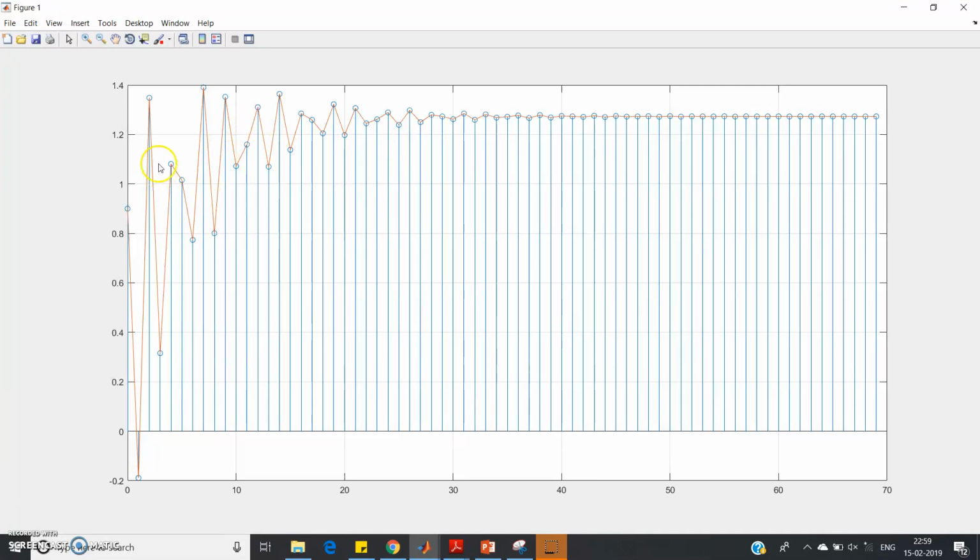So this is the transient response, and it is very important to analyze the circuit. Obviously from this it is clear that the transient response is there for a very small span of time, and for the huge span of time the steady state response is there, but the transient response is very important from the point of view of designing a system. Suppose you take the same example: when you turn on the switch of the motor, suddenly it draws a very high current. The current should not be so high that the motor burns out, right? So to control that, we should design the system properly.